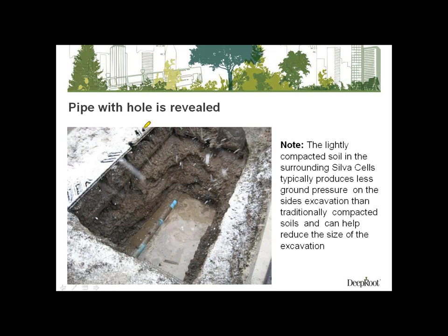Another thing to point out is that, and this isn't going to be in all cases, but it's important to point out that because the soil in the Silva Cells is not densely compacted and it's typically not a very dense or heavy soil, you don't get all the soil pressure around the outside perimeter of your excavation, and it's soil pressure on the outside that helps push in the walls of the excavation.